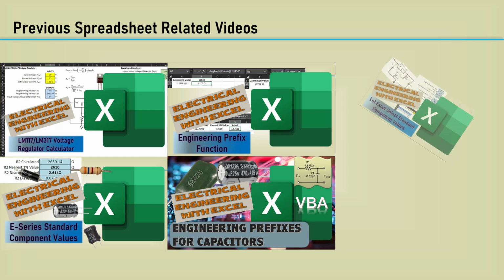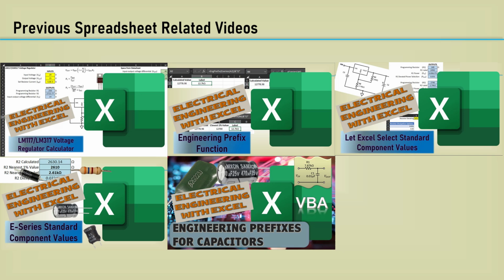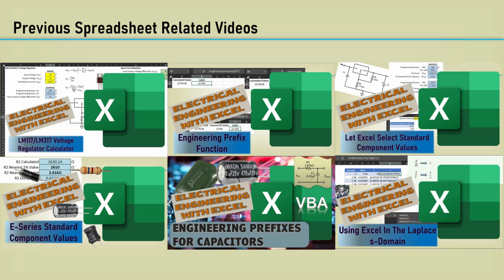Another spreadsheet was developed to select standard component values, the SI prefixes with units, including the D-rated next highest power rating of resistors. We made Excel work in the Laplace S domain, where we made Bode plots for a simple network. We will use this methodology to make Bode plots for this Sallen-Key filter using the standard component values calculated. If you haven't watched these videos, most of the spreadsheet application we will lay out in this video may not be obvious.